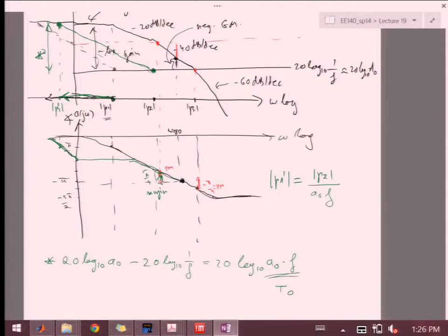If you have this one dominant capacitor you're adding somewhere to create a pole, the others are not going to move by much. And so you can do calculations this way to figure out what your P1 previously was, and then what you need to add to move P1 to P1 prime. It's basically this new value.